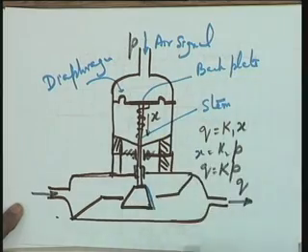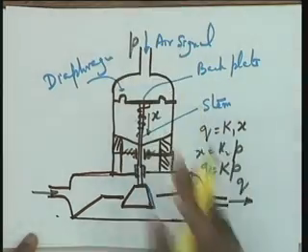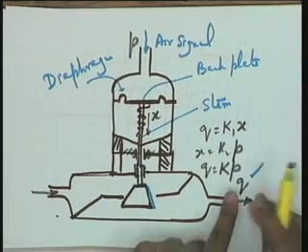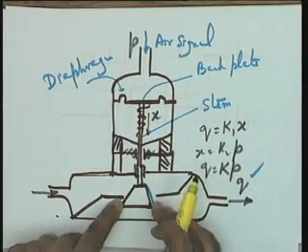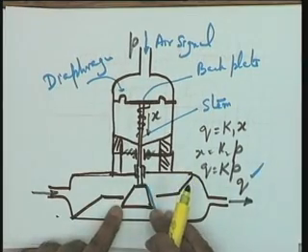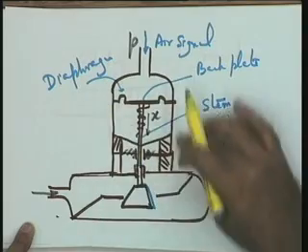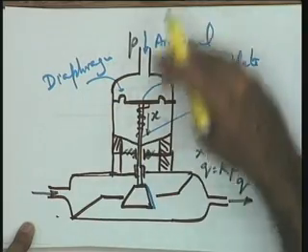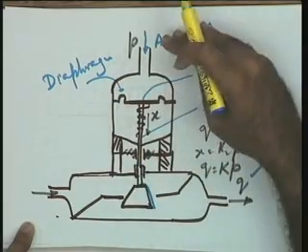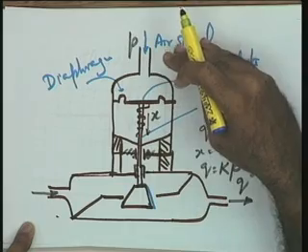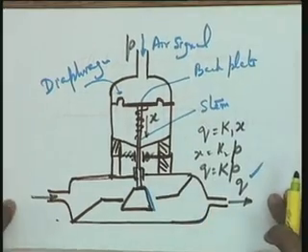So, you see that it is a reverse designing. You should know what opening range you require, and accordingly design your system so that with the range of 3 to 15 psi gauge pressure, you are able to realize this objective.